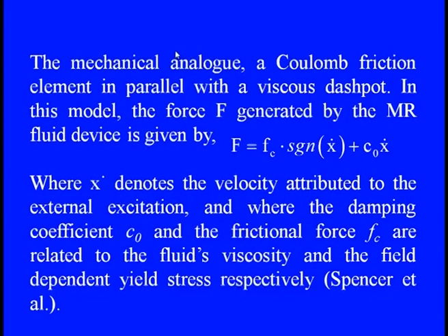So, we have two things together: the damping, which is a function of the fluid viscosity, and the frictional forces, which depend on the field, that is, the yield stress fields. Along with that, this Fc, the frictional force, varies with the sign function of x dot.